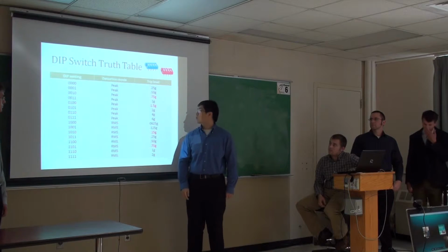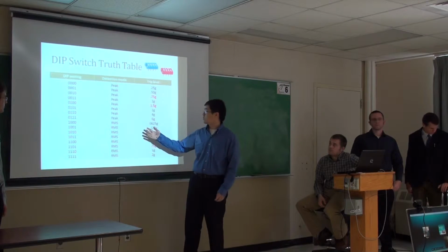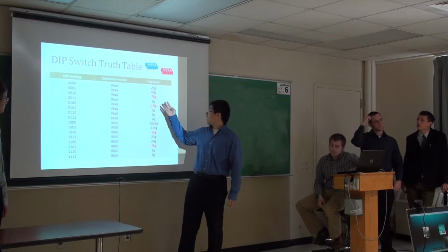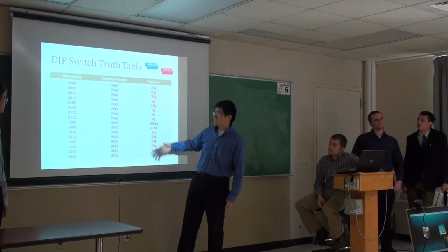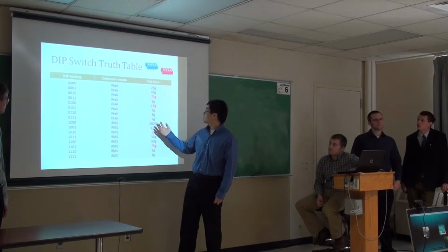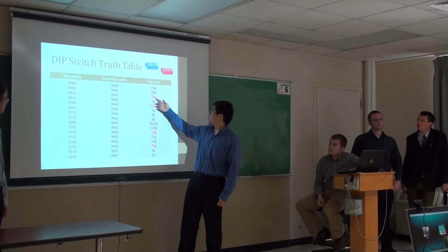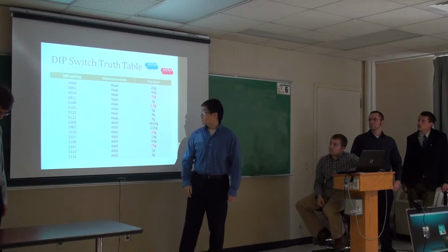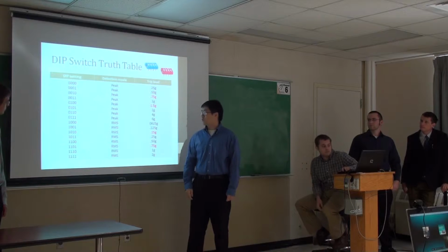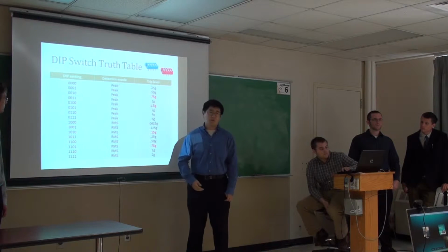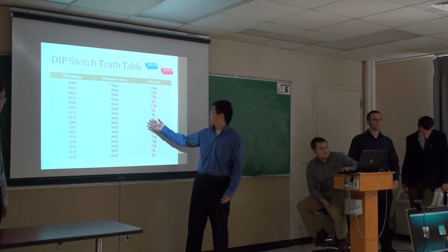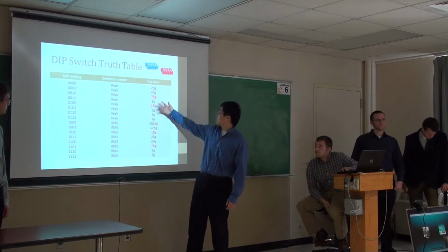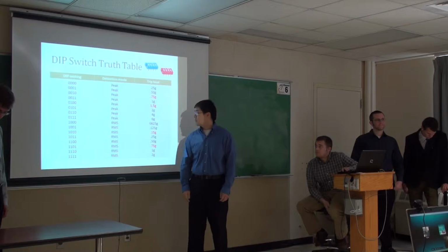One issue we had when we were doing this is that because we're using 4 bits, that leaves 4 extra settings that just weren't assigned. So we assigned extra settings, 0.75G and 1.5G, to the unused dip settings, to avoid confusion with the customer and to make programming a little easier for us, so that the customer can have better resolution in their trip setting levels.